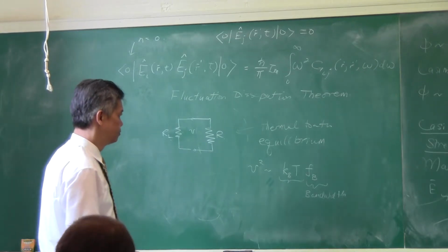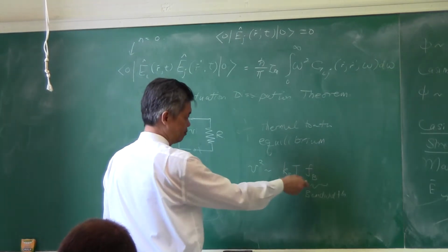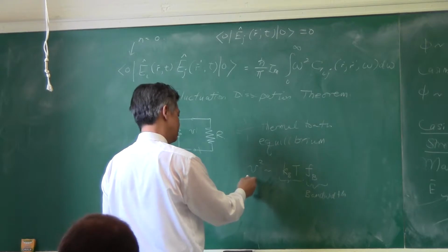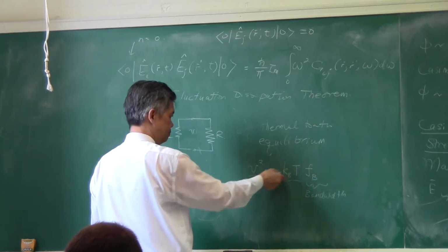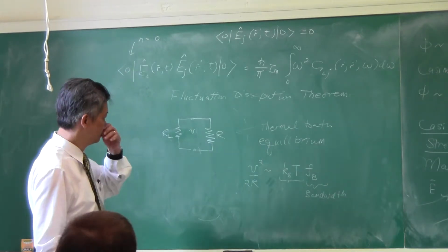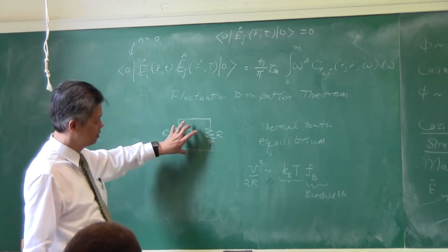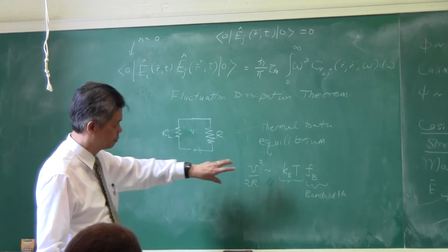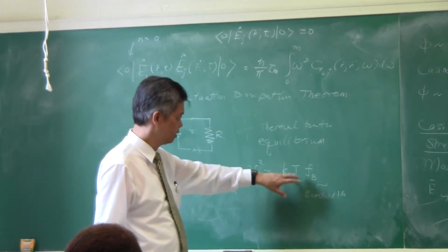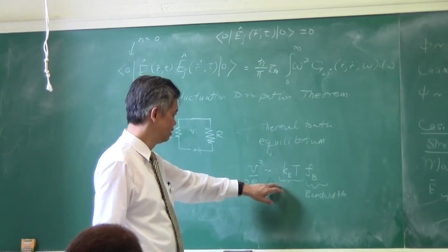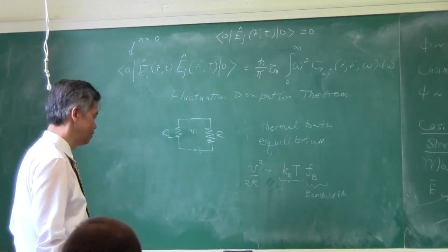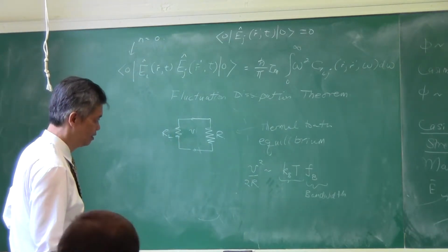So this thing will be in terms of watts because you multiply by this frequency. So this is like V squared over R kind of thing. It will be proportional to that quantity. And hence the thermal noise that you acquire from the environment is always proportional to temperature. It's always proportional to the bandwidth of the signal. And this law is actually a special case of Planck's law.